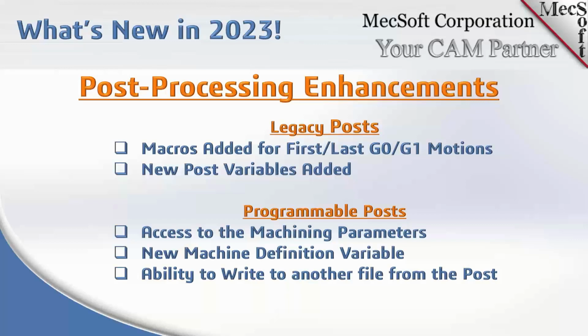So we can actually inquire parameters of the machine tool, like in tolerance and out tolerance and stock left and things of that sort, from inside the post, which can be very useful. And then we also introduced some new machine definition variables that the post can use. And finally, the ability to write to another file from the post directly. So you're not necessarily restricted to posting to the selected post output file. You could actually write to an external file if you wanted. Some users have requested us to be able to do that. So that was a change there.